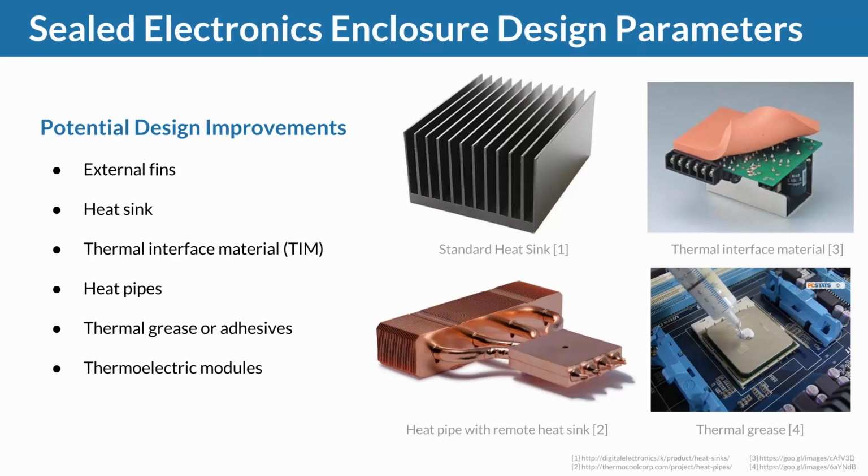But I like to start by looking at sealed enclosure design, because from my perspective, the challenges here are even bigger. On the one hand, we have no option to actively cool. We can't put fans in there, and that significantly limits the number of design parameters, the design space, that we can use to improve the thermal performance of the enclosure, to make sure that the chips we're putting in there never pass the temperature limit where they start to fail.